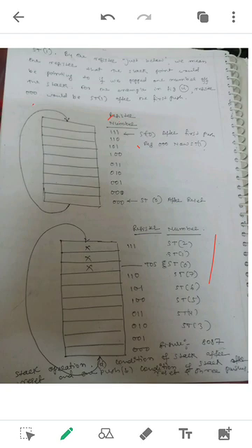So for 3 pushes, you can see the TOS is initialized here. So the ST0, ST1, ST2. For 3 pushes, the top of stack is ST0. That is shown in a circular fashion. It is operating in the stack of the 8087.